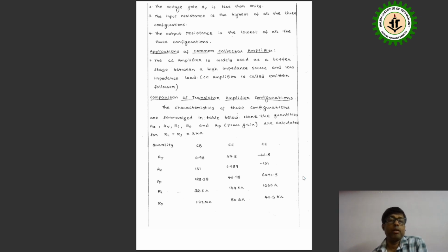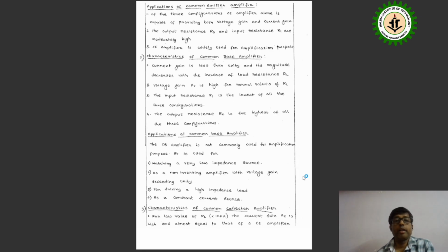Using this hybrid model, we can discuss different types of circuits when we go to oscillators and multivibrators. It is very easy and suitable to draw the equivalent circuit under the h-model. There is also the difference between low frequency analysis and medium and high frequency analysis, and we can also draw the electrical equivalent circuits.